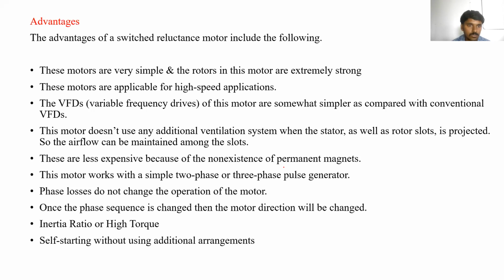Achieving variable voltage and variable frequency is somewhat simpler than with other motors. This motor does not need any additional ventilation system in the stator as well as the rotor slots. Some motors need ventilation for cooling purposes, but this is not needed in the switched reluctance motor because we are not using any winding in the rotor slots. We are not using any winding in the rotor circuit.